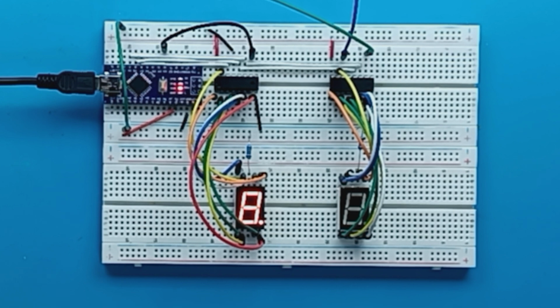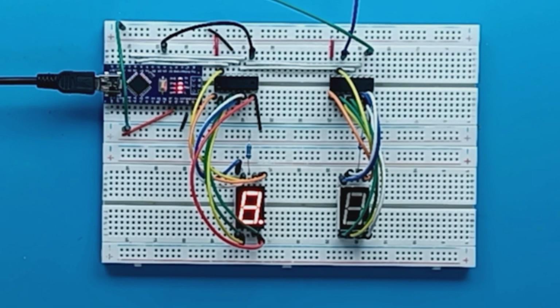So here I reset, and then my demo basically is just a little loop which writes 1 into the first register, second register, and it does it for 16 registers with a 100 millisecond delay. And then every time we clock a piece of data, we latch it into the display. That way we can see the progression as we go through.